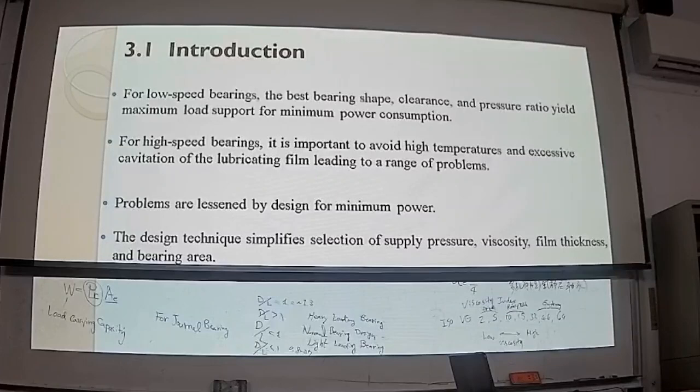For number 2, number 5, or even number 10, they are mostly used for the spindle or a big rotary table with a very large bearing head. For 46 or 64, usually they are for the slideway system. So depending on your moving speed, you can decide which viscosity is for your lubricant.